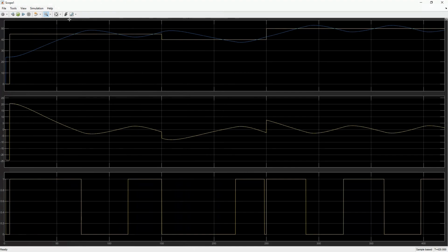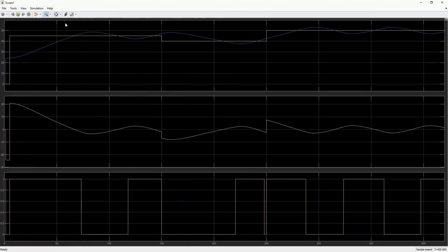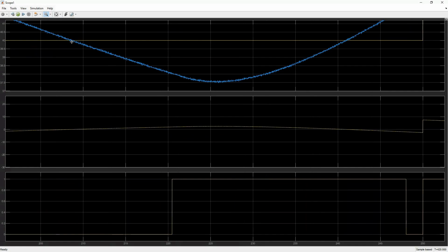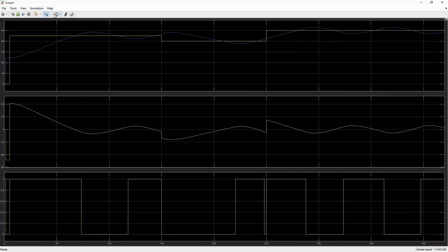This looks a lot cleaner, right? Look at this. This looks awesome. So again, if we zoom in to some regions of interest, maybe around here, you can see that even though it was noisy, and it's chattering up and down, we are not getting the chattering behavior. And again, that's because I chose a deadband size of, I think in this case, 2 degrees.